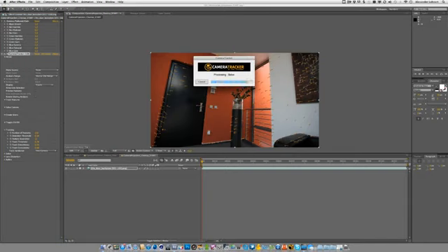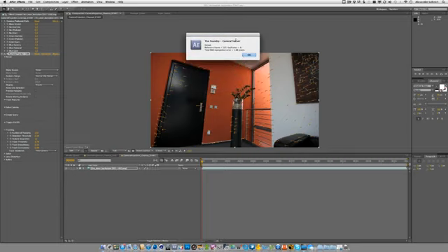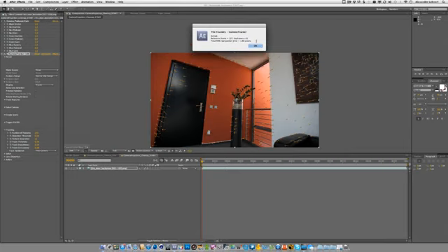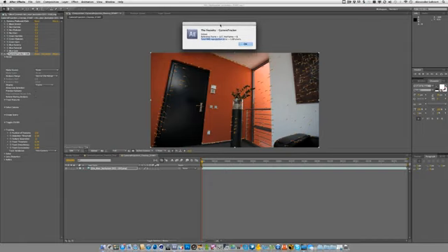That just takes a little minute, and after the solving we just got the information that our RMS projection error is at 1.68 pixels. This value, just to bring that back to your mind, this error is saying how much the 2D track points might slide from the 3D projected position in space. So 1.68 pixels is quite heavy for that. I just want to hit the 1 pixel mark at least.